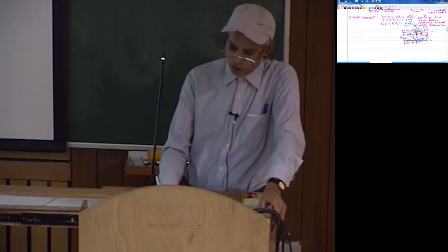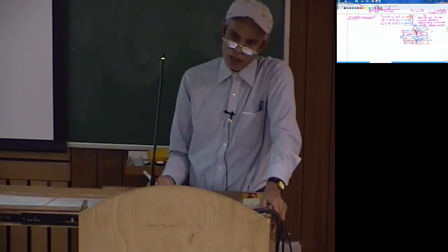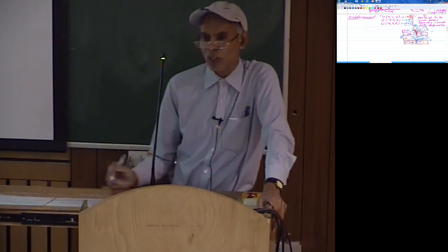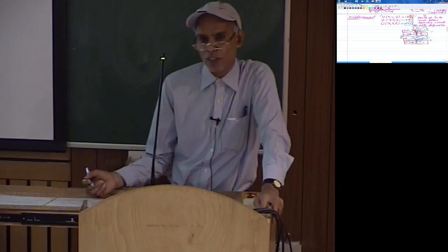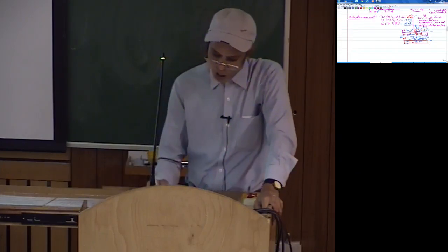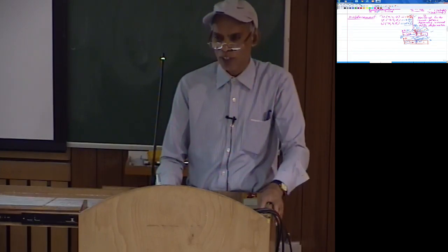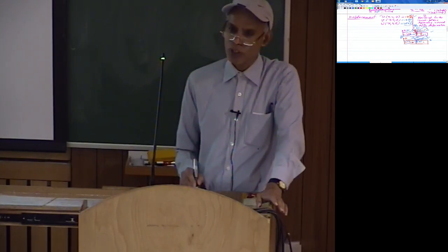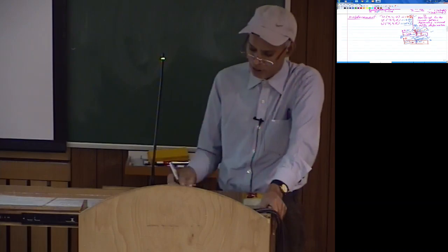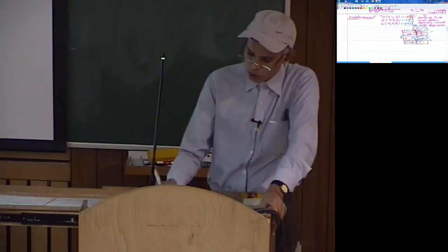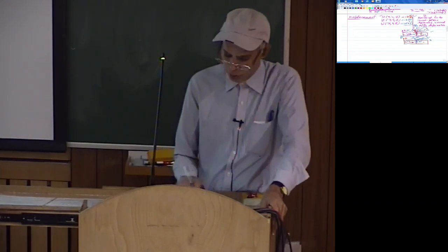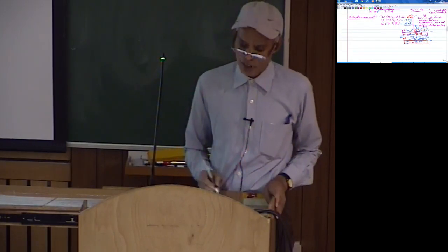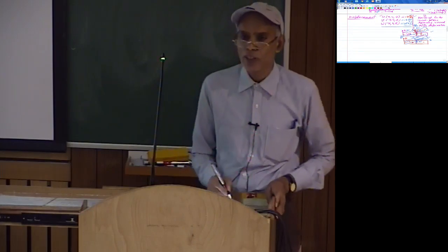Here you can call this theta x and this theta y. Then you will also have transverse shear strains. That is known as Mindlin plate theory, or first order shear deformation theory. You can take higher order terms here, maybe a z square term into some function, z cube into some function. Those are referred to as higher order shear deformation theories. That I am not discussing here; I just wanted to discuss how the formulation will proceed for a typical plate bending element. So this is the first step, the approximation of the displacement.